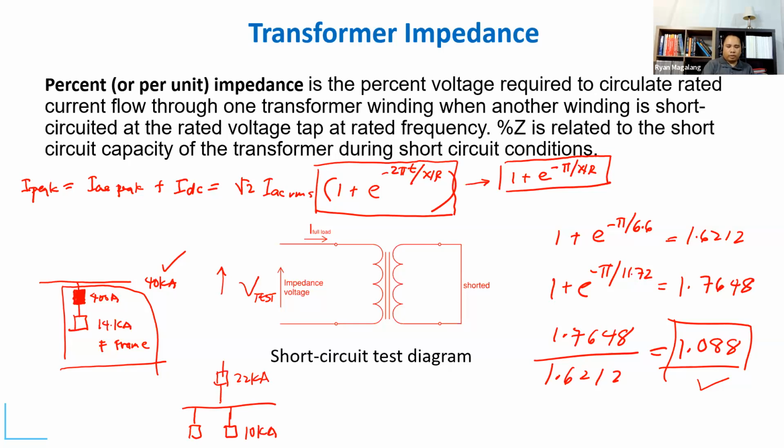Normally, what I see most of the time, all of the breakers, the main including the branches, are rated to be the same, and the panel also. So if let's say the panel is rated 32 kA, you would see that your breakers are either rated 32 also, or a little bit higher, maybe 40.